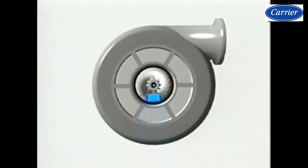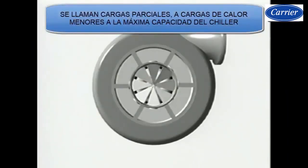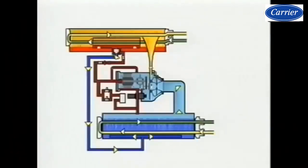we have. Let's remember that it is very important that the chiller can maintain a good performance at loads below 100%, because statistically it is known that most of the time the chiller works below 100%, so the compressor has to be regulated. It has to be able to adapt to what the application is asking for. That is done by the centrifugal compressor of this chiller that we are studying, varying the radial inlet of the refrigerant that comes from the evaporator, in this way it will also meet the demand.